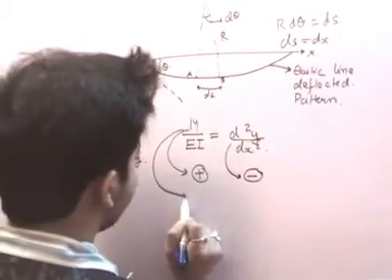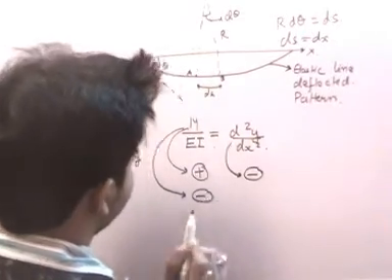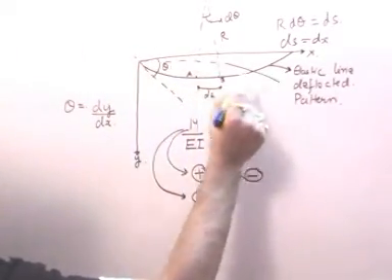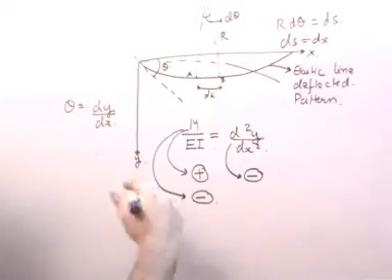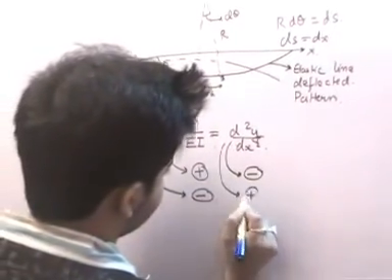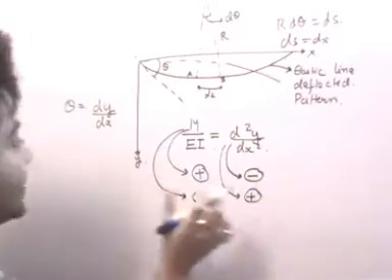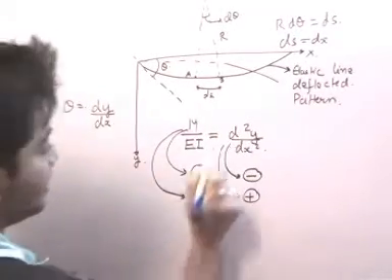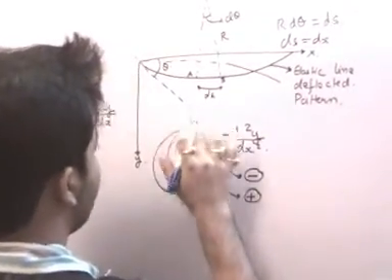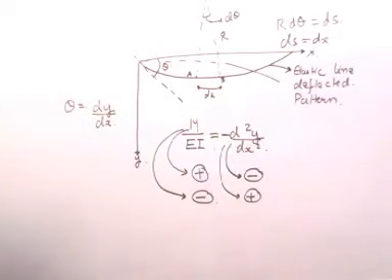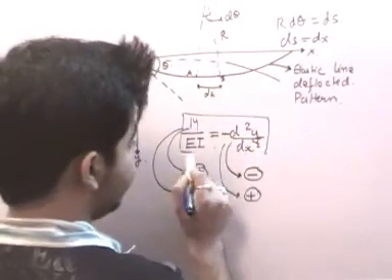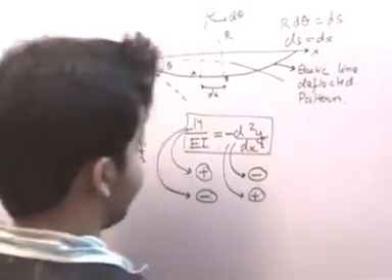Now in case of a hogging moment, we will see a negative moment, and the shape of the curve will be like this. So it will be an increasing function of x. So effectively we see opposite signs, and I can put this as negative and place the normal value of the bending moment. So this is the differential equation of the elastic line.